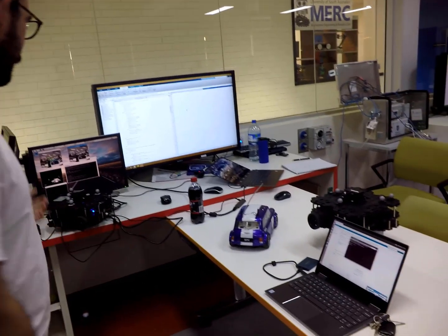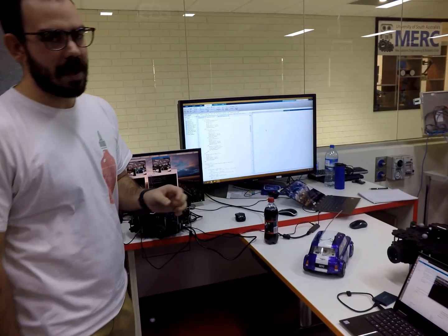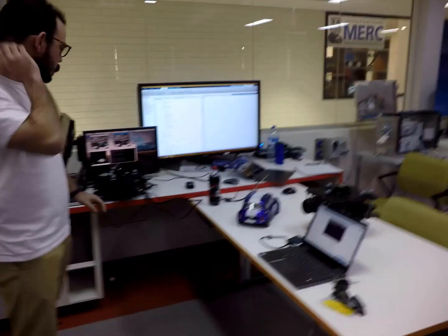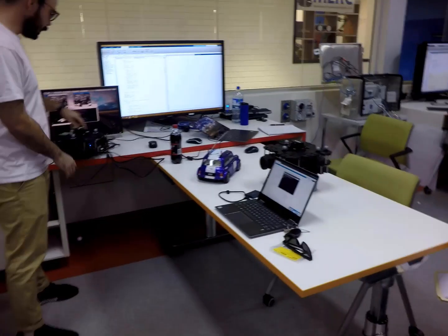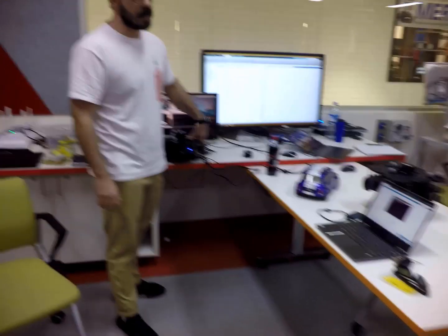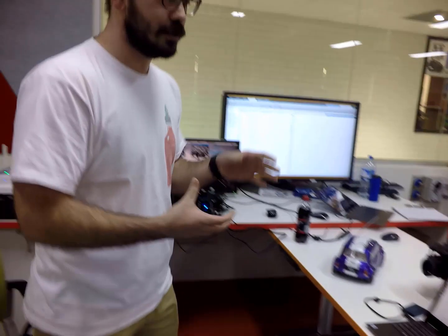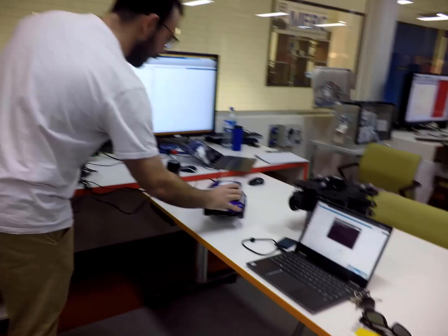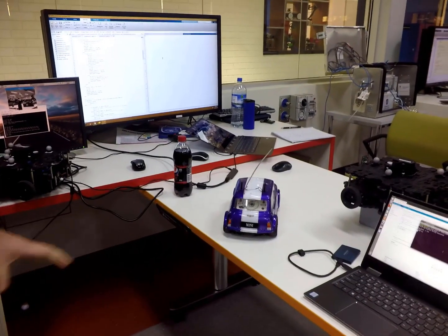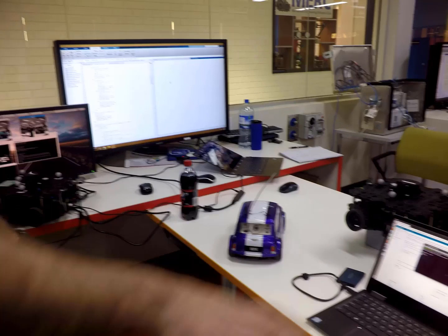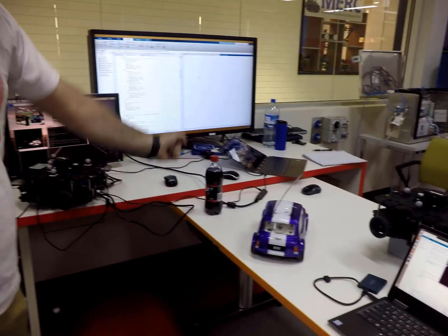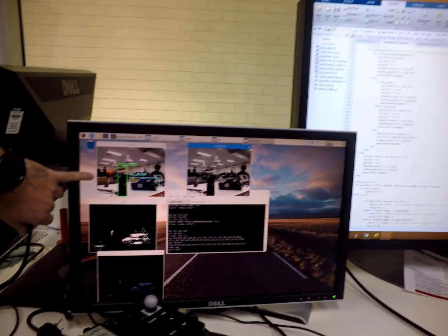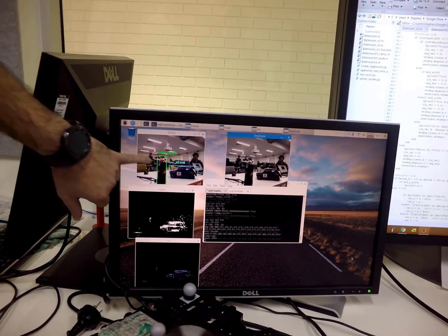Obstacle avoidance, but using machine vision and purely the camera as my mode of detecting an object. As John spoke about, we're using the neural network computer to run a convolutional neural network to decipher between a lovely healthy bottle of Pepsi and a car in real life. So the idea is, with it being dynamic, the car can be driving along and the bot follows the car. You put the bottle of Pepsi in front of the bot and the bot will drive around it and continue following the car. It's showing a frame of the camera and it's showing that it's got a bottle detected and